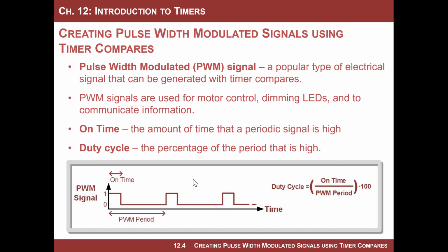And so when somebody comes up to you and says, I have a PWM signal, and you go, oh, great, you've got to ask, what's the period and what's the duty cycle? And from that, you then know how to sketch out what its waveform looks like.